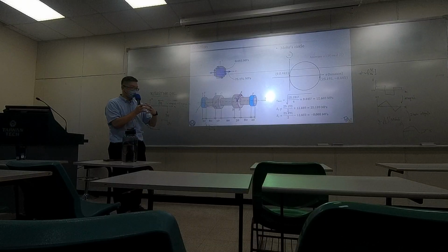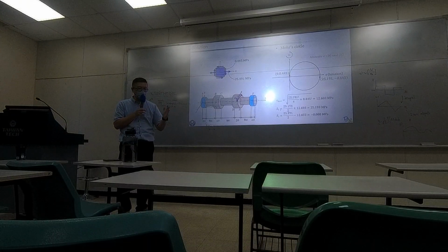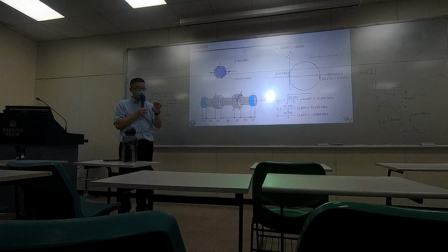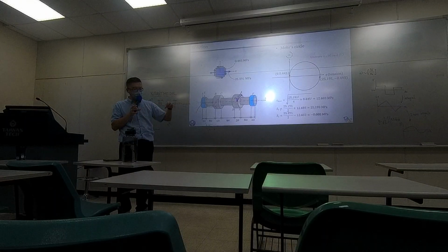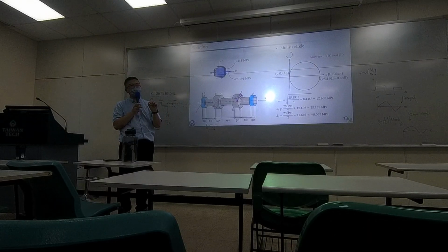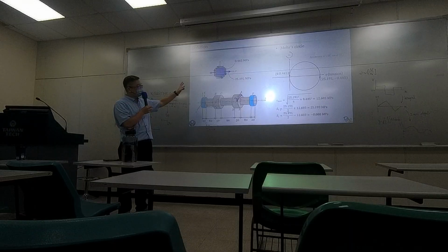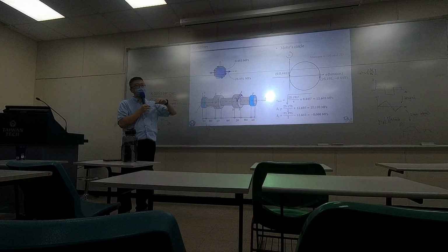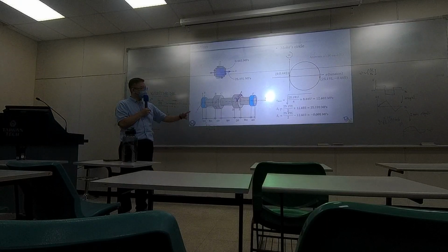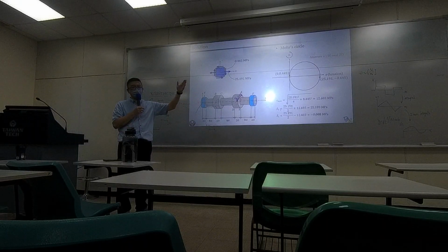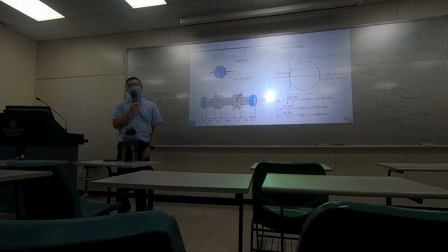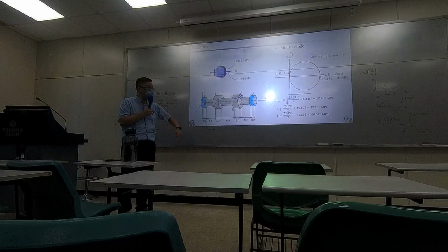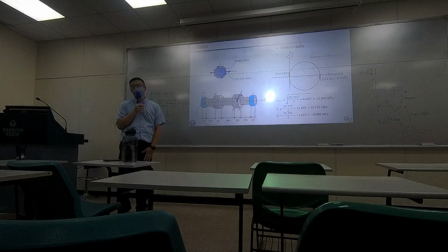You have components, you figure out where has the maximum moment, you figure out on that particular geometry at which point is carrying the largest normal stress and shear stress, perform Mohr circle analysis, and you figure out the principal stresses and the maximum shear stress. And later on, for the design equations, those values will be used.